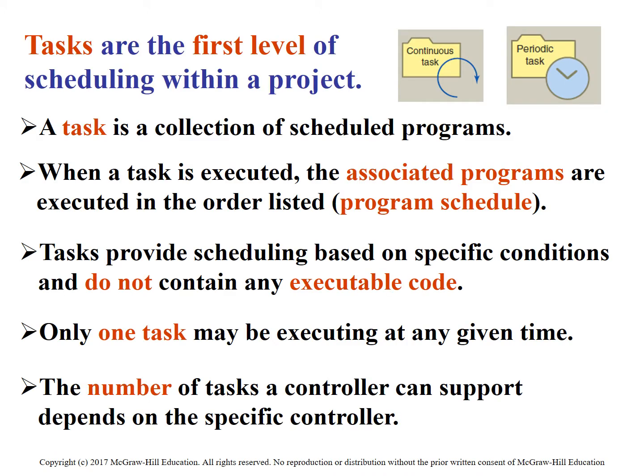So tasks, this is something that we're not really going to get too much involved with in this class. It's more of an advanced type solution, but the idea is that you can have a routine that runs continuous, like you would typically have. Most of your programs are going to be in a continuous task. So every time this PLC scans, it runs all of the different programs or subroutine programs that you have available. You can set it up so that there's a periodic task, so it only runs those tasks when requested.